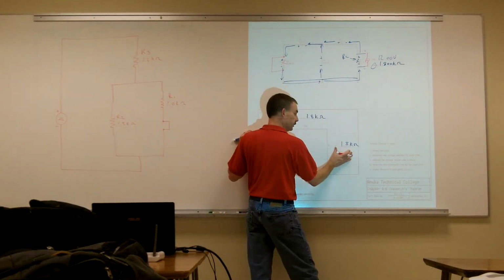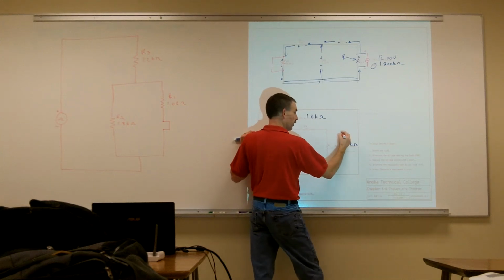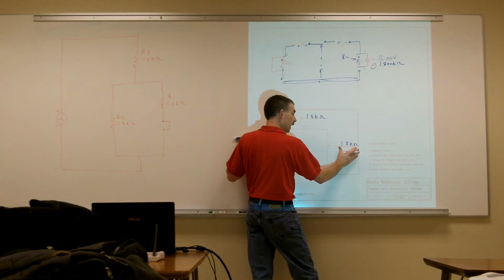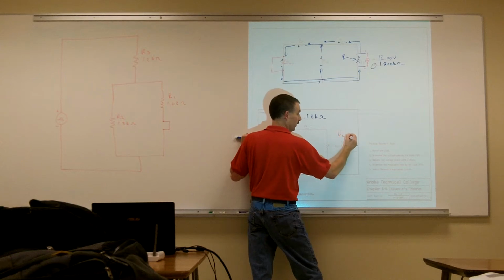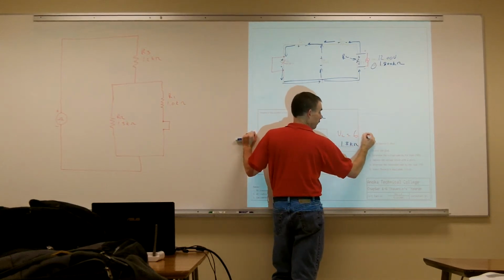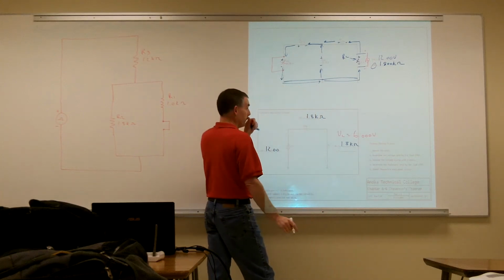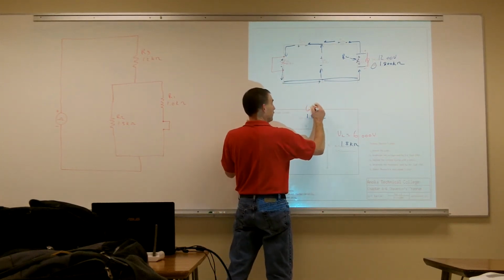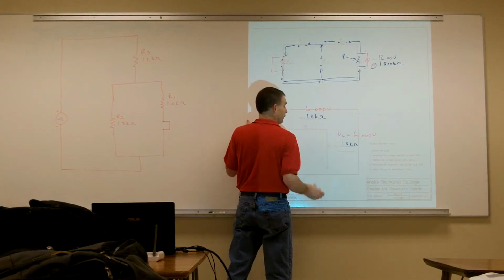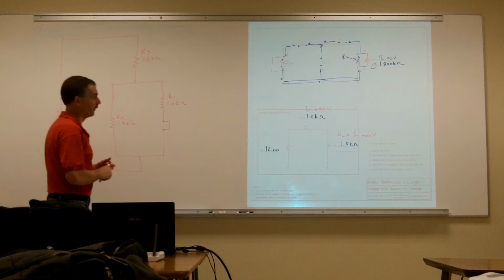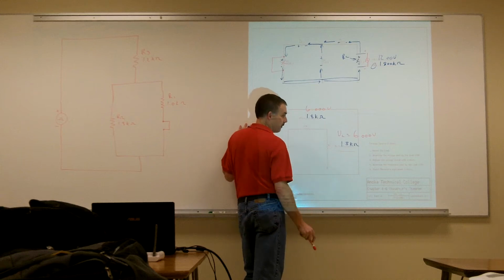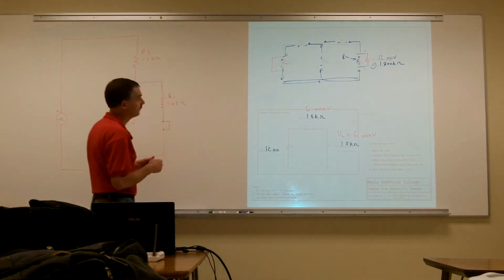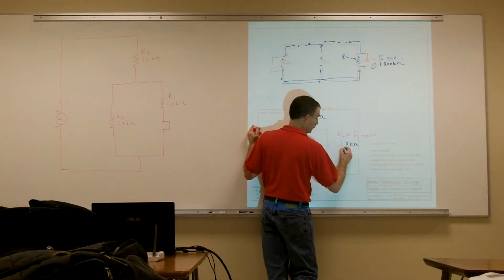So first of all, we should find the voltage going across our load. I should put a line in there because I've done that before. So first of all, find the voltage across your two resistors, so we know that my voltage across my load is going to be my 6 volts. The voltage across my Thevenin's resistance is going to be 6 volts, since they're both equal. Now we have enough information to find my current. So now we just take our 6 volts divided by our 1.8 kiloohms, and what do we end up getting? 3.3 milliamps. 3.33 milliamps.